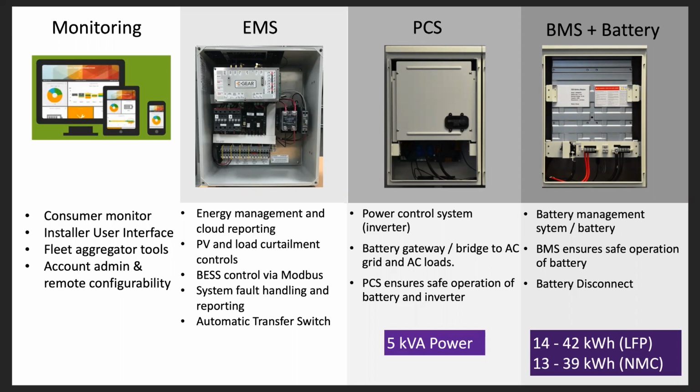Can a solar plus storage system also charge from the grid as well? Yes, it can. It can charge from the grid, and in fact, our low-level battery maintenance features that are built in, for protection of battery health, will actually pull a low-level charge from the grid if there's no PV for extended periods of time, or else shut it down. Also, it charges from the grid when the auto recovery feature kicks in.